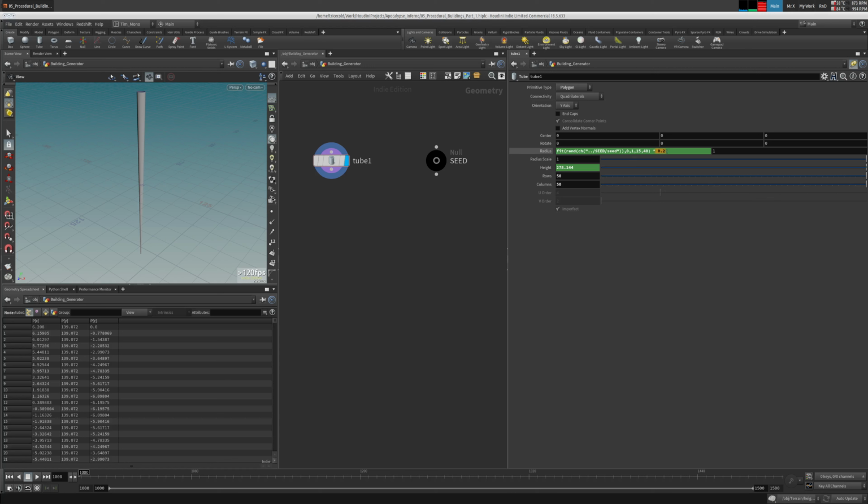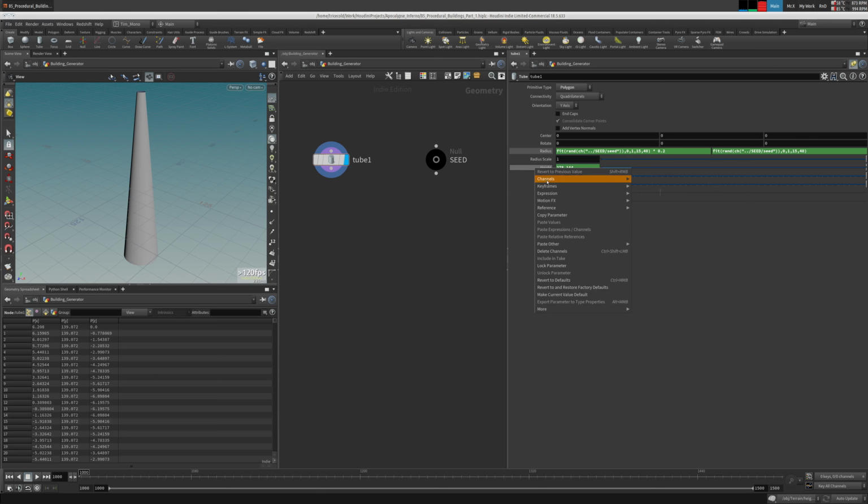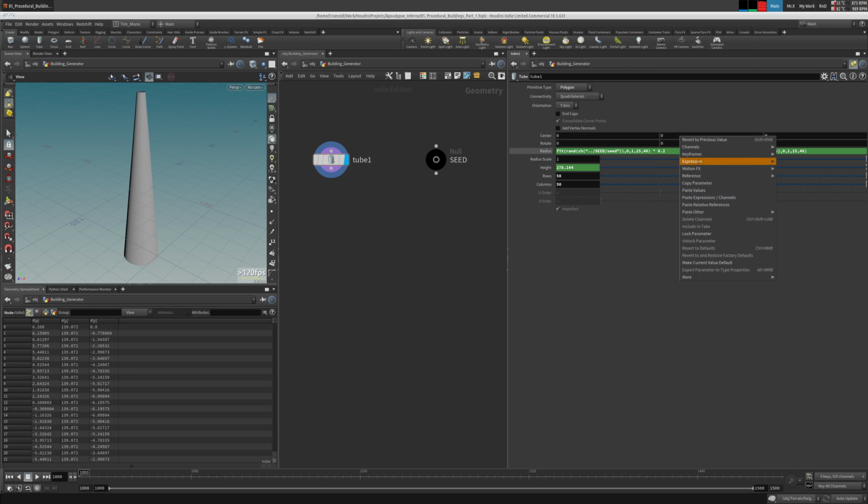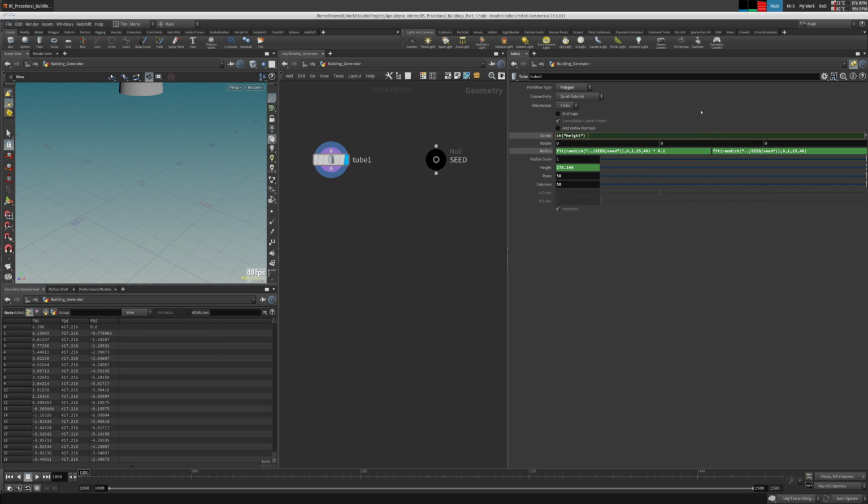I guess I didn't like one and I made it smaller. Now let's get the base radius, which is 0 to 40. And you want to get the total height, divide by 2. So right click, copy, paste, divide by 2, so it sits on this position.